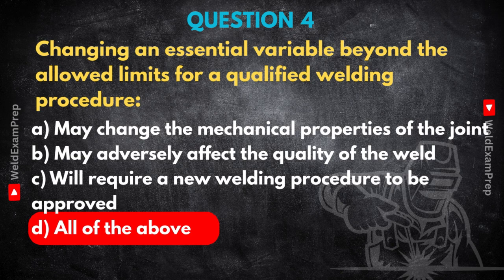And affecting the quality, that seems almost obvious if you're changing something fundamental. It is, yeah. Weld quality means it's sound, free from unacceptable defects, fit for purpose. Changing an essential variable could introduce defects, maybe more risk of cracking, porosity, fusion problems, or it could just degrade the overall integrity in ways that aren't immediately obvious as a distinct flaw, but it's just not as good.